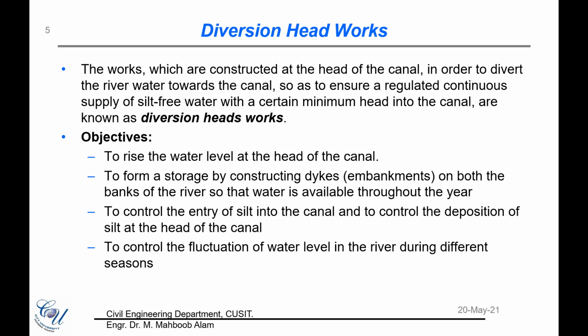In addition to the quantity of discharge, the diversion headworks also ensure that the water is mostly silt free. There is no silt in the canal, so that when the water reaches the tail end, we do not have a problem of siltation in the channel. So we try to install certain structures which stop the silt from entering the channel, and we'll look into these structures as well.